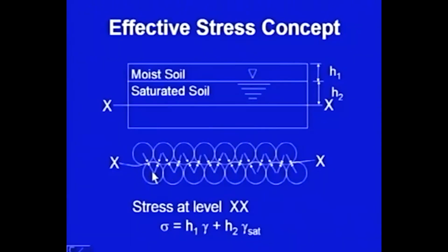All these particles are in contact with each other, and where they touch each other, they will be exerting intergranular forces. So, at this point, at this point, at this point, the intergranular forces will be acting. The stresses in the soil mass will be transferred through these intergranular forces.